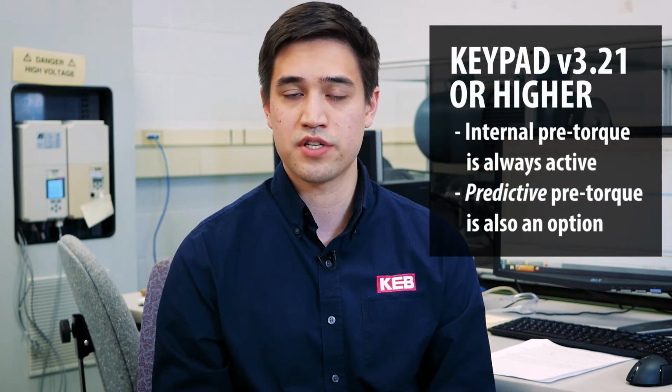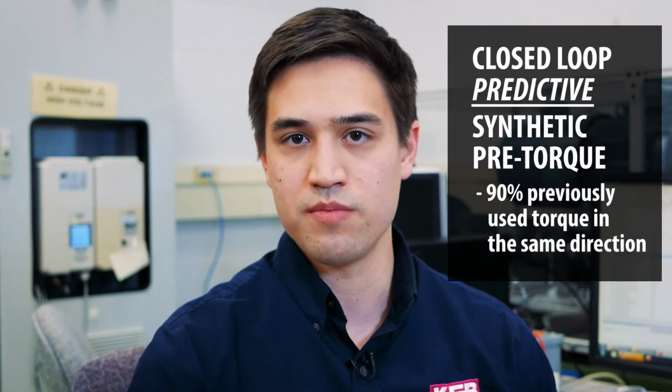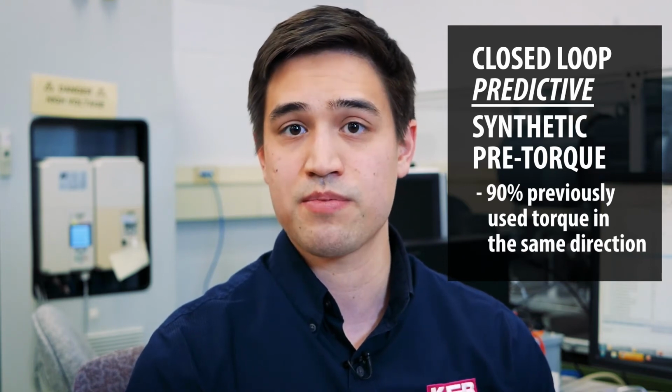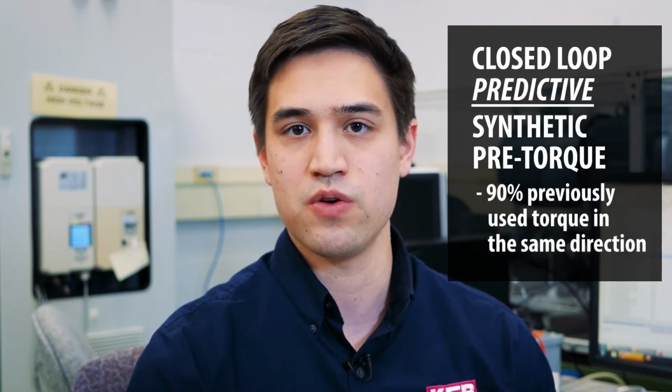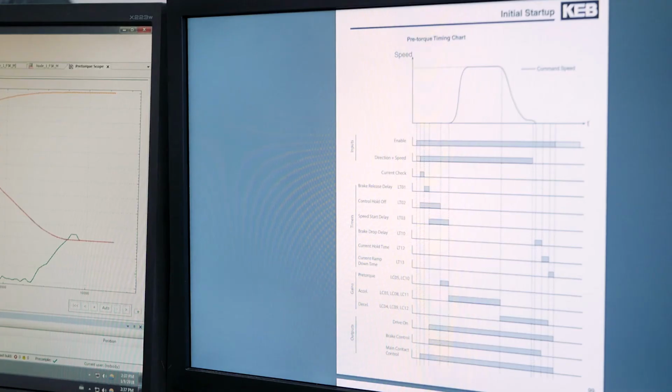However, there is another function known as the predictive pretorque which you can activate. In LC01, if you set it equal to 5, also known as closed-loop synthetic pretorque, the predictive pretorque is turned on. With predictive pretorque on, the drive determines the load in the car and then uses 90% of that value for the pretorque value for the next run in the same direction. Typically, internal pretorque is sufficient for most applications, but if desired, predictive pretorque can be used to provide additional ride quality.